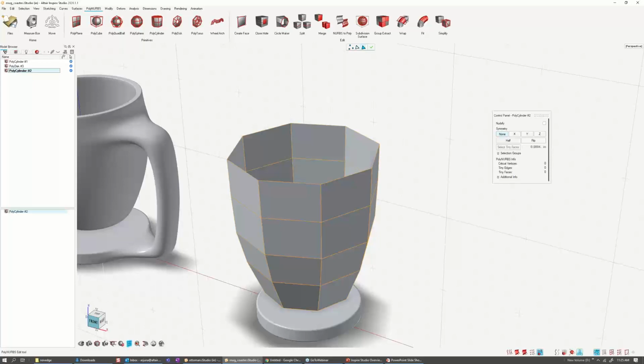So now I can go ahead and add some thickness to this. In the same faces mode, I'm going to select all faces. And I'm going to go to one of these interior faces, or the inside of any face, and just click and drag inside. When I move my mouse, you can see that it's rotating slightly, but as you move closer to the axis of it, the blue dotted line becomes red, and that means you're going along the normal and you'll be fine. Then I let go of the mouse and type in a value of 0.5 or even 0.75 inches